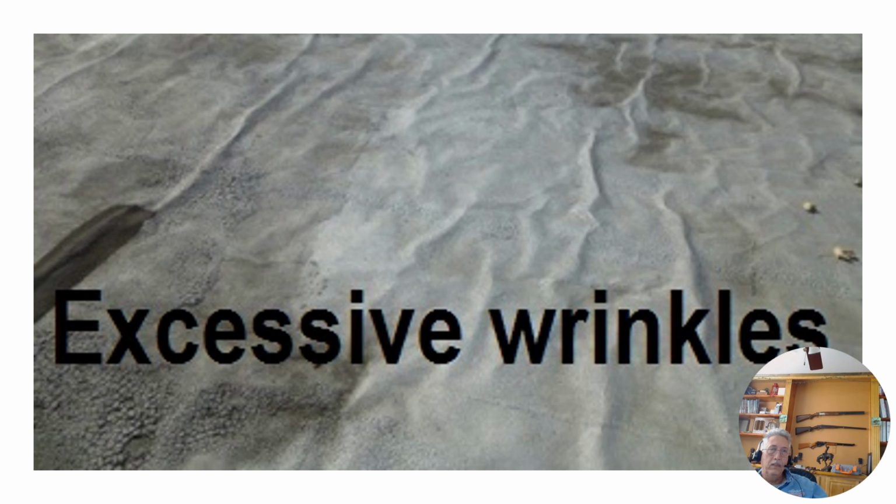Excessive wrinkles. This is an old roof, and when they get old, they wrinkle up like that. Another indication of age in this type of roof. See this hole here? And there's a bunch of schmutz in there, so that was probably algae and stuff growing in this deep hole. And there's probably rot under there, right? So you don't step in these holes when you're doing these roof inspections, because you could fall through. Walk around them. But that other hole was full of water, right, that we just looked at, and this one's dry. Why do you think that is? So it could have been shallower, maybe that's the reason, or maybe there's a hole in the roof and it's dripped through into the building, right?